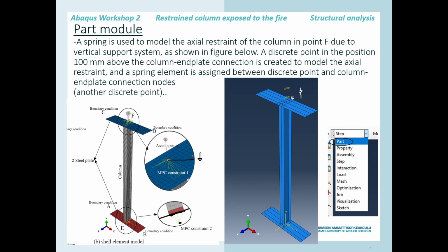So we model the geometry in the part model, and we try to keep our 0 0 position for this one. We will model using the exact dimensions for this reference discrete point, which will be easily available in the assembly model once we go to that. Okay, so now let's go to the part model first and then create those 6 parts.